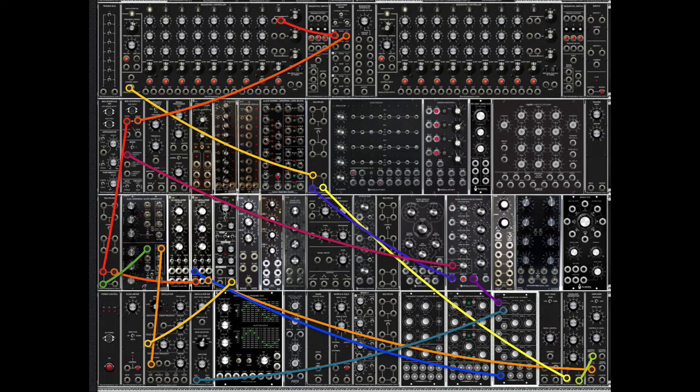And this is now going to be changing the pulse width of the square wave. This knob here will control the intensity of it, as will this. You could modulate this. It's got an input to modulate that. Another thing you could do, in addition to this, is this will track 1 volt per octave. So if you take your pitch output, pitch CV, and plug it in here, now each individual key will change the speed of the LFO, modulating the pulse width.